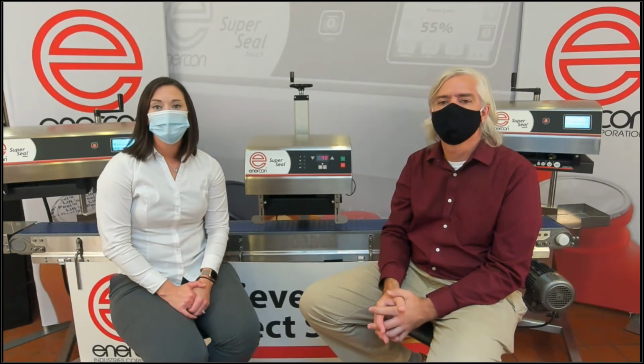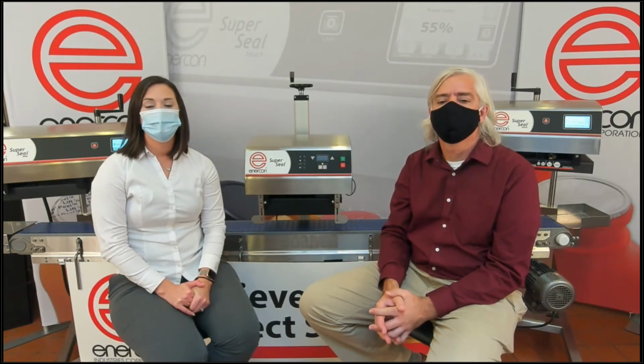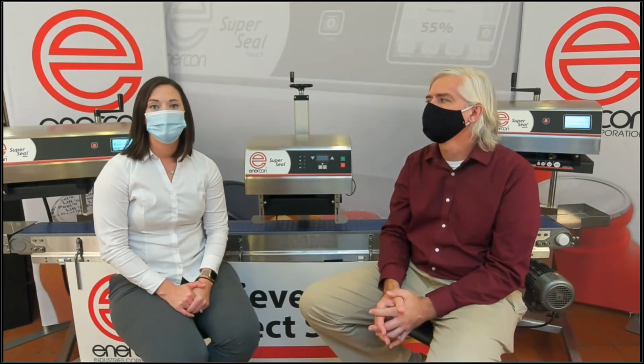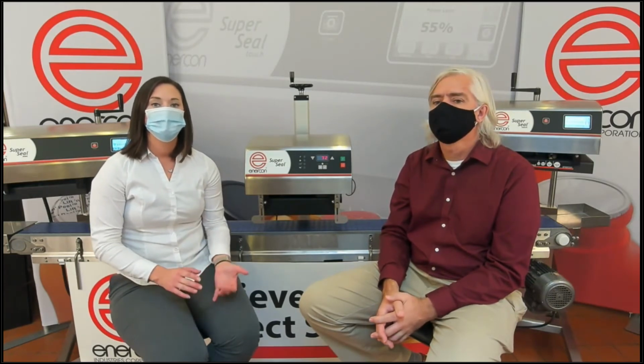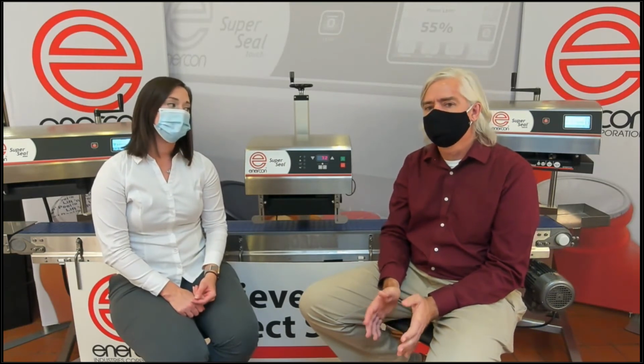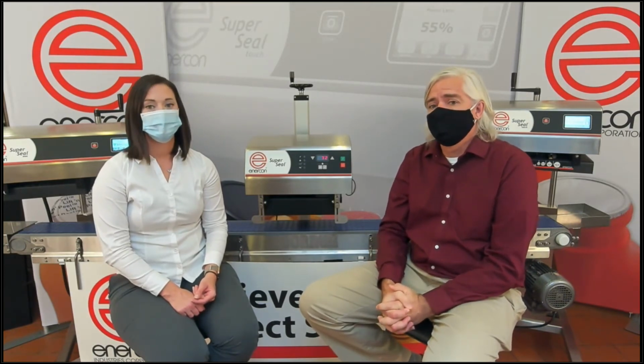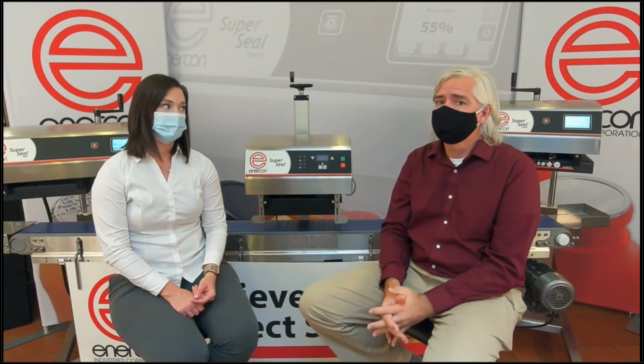So thank you again for joining us. Just to recap, a few of the things we went through today to help you find and achieve your perfect seal. Make sure your cap torque is proper. Make sure your sealer is set up properly. Anything else you want to add, Jeff? That pretty much covers it. Make sure you've got good products going into it. So if you've got an unknown liner and it's not acting right, there's a good chance it's a problem with the liner. Something has changed.